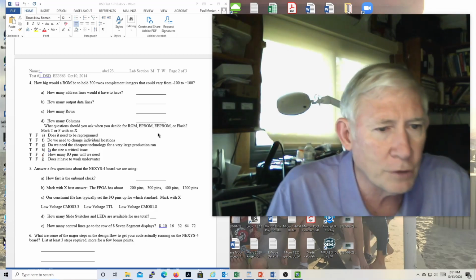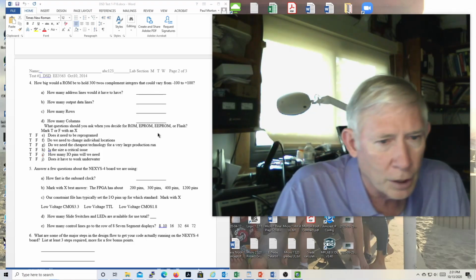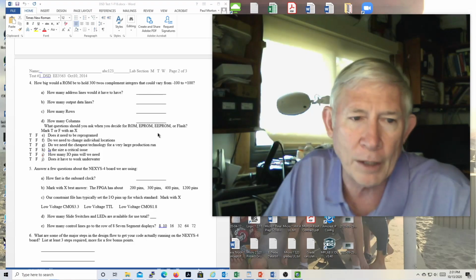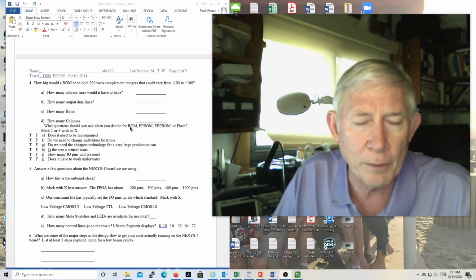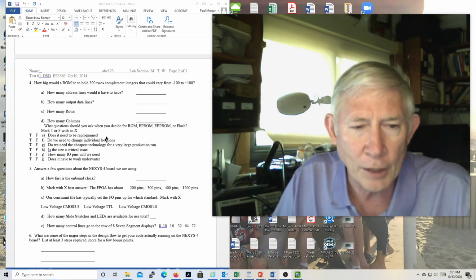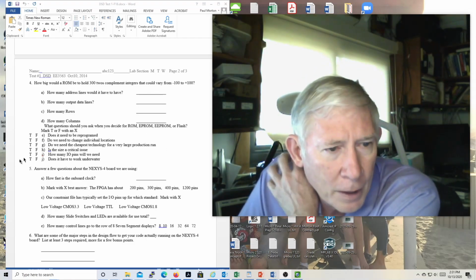Do we need the cheapest technology for a very large production run? Yes, that's another good question. You would probably want to ask that and make sure that you ordered a read-only memory if you were going to do that, because you don't need to reprogram it and you want to get the cheapest you can, and it's going to be a very large run. So then that would justify factory programming.